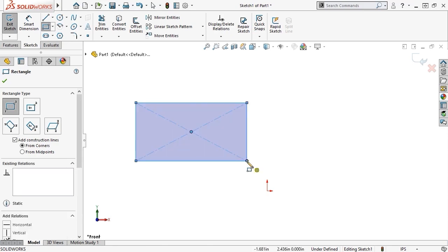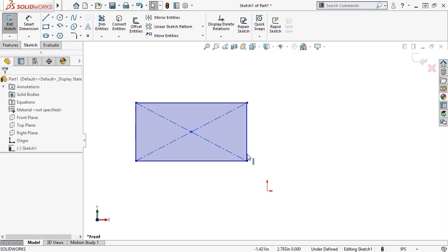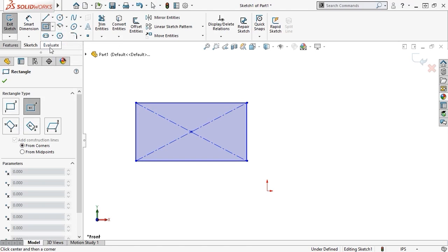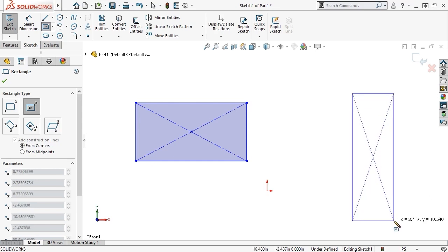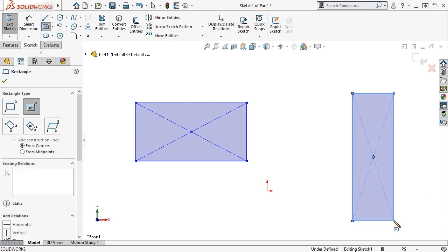This one is really straightforward, but as you work with other rectangle tools and other sketch tools for that matter, it may not be quite as clear which selections you're supposed to make. If I switch to the center rectangle, notice that the first point I'll be selecting is the center, and the second point will define the size. So I'll click once where I want the center to be, and click again to create the rest of the rectangle.